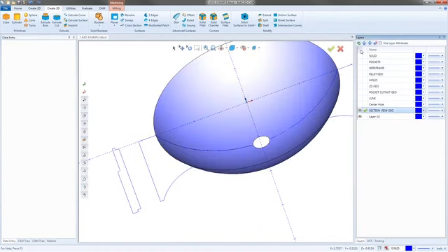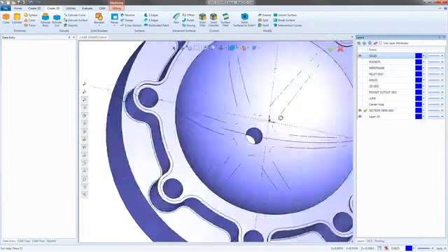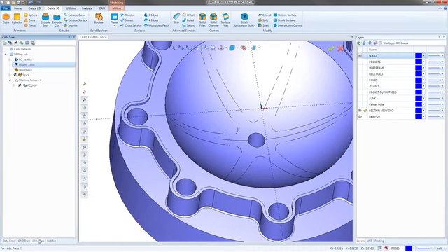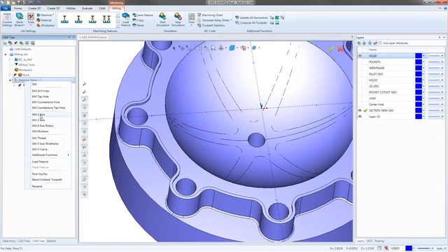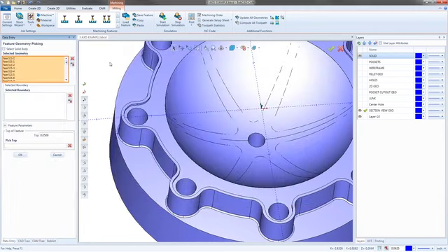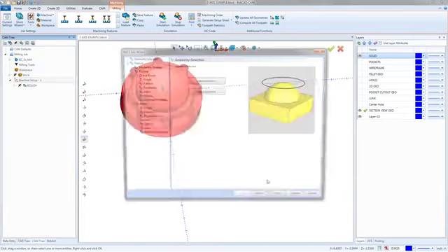So now if I turn this on and I turn on my actual solid model here, we now have a cover for that entire area. So now there's no way for the tool to get inside those pockets again. Now when we go to our CAM tree, we can right click on machine setup and then go down to the mill 3 axis. Select the geometry. I'm going to pick the whole thing again because whenever I do 3 axis, I pick the whole job every time. Hit OK.